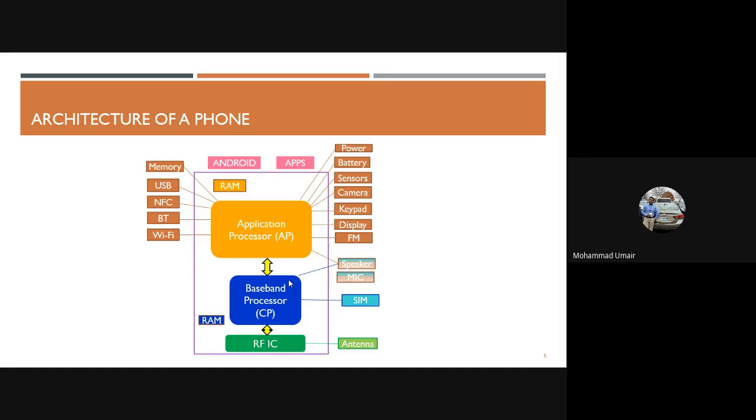So again, the placement of that antenna plays a very crucial role, because these antennas are so sensitive that if you hold the phone with your left hand or with your right hand, you are going to cover a certain portion of the antenna, and that impacts the amount of power that can be transmitted by the phone to the network, or the amount of power that can be received. With that change, all your internet speeds and audio qualities are going to change. So the placement of these components on the phone, whether one component sits on top, on the left, or on the right, is very crucial.